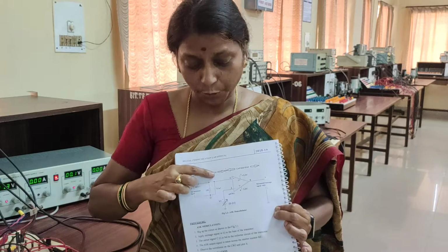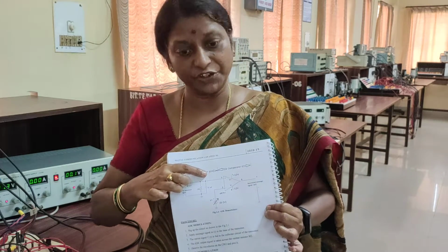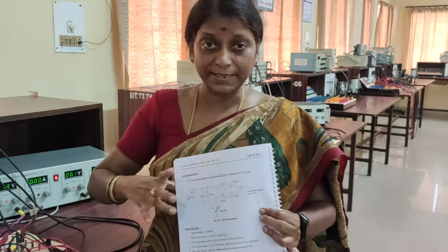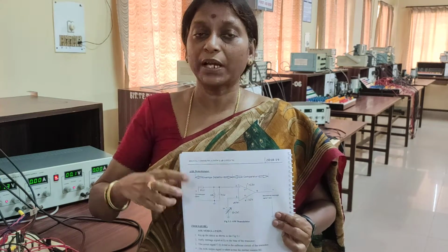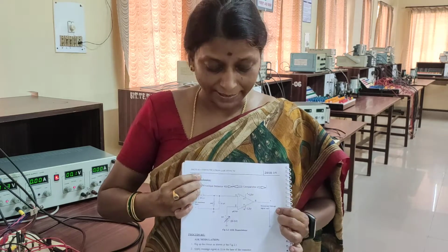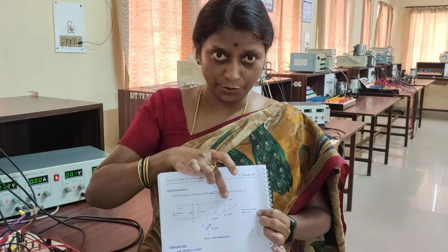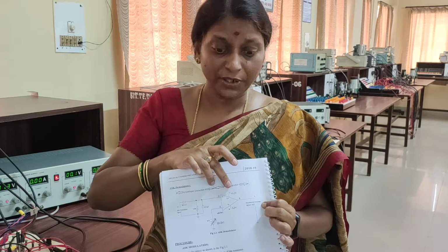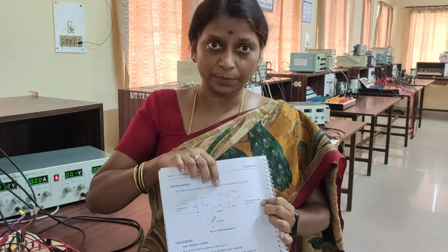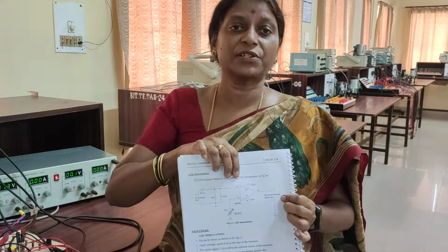So at the output of the envelope detector, you will get a charging and discharging waveform with certain amplitude. So to recover back the original message signal which we have given, since we have given a NRZ data, or the +5 is a positive logic and the -5 is 0. So to get back that one, we are using a comparator circuit here, op-amp as a comparator. So here output of the envelope detector will be given at pin number 3. This is a non-inverting op-amp circuit as a comparator. So output from the envelope detector is given as an input to pin number 3, which is a positive.